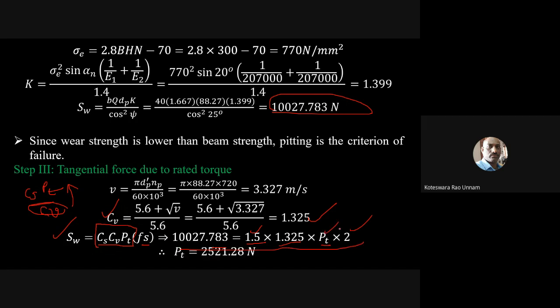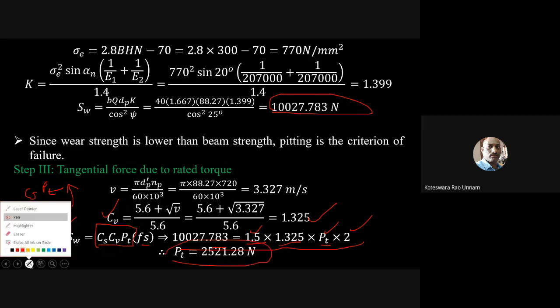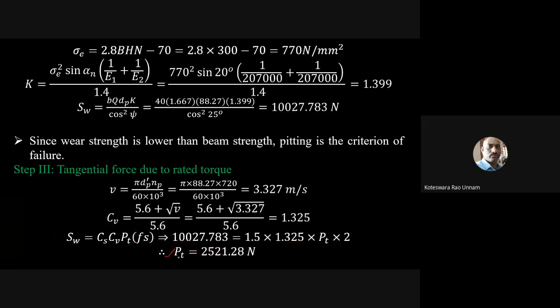Once you have PT, then you can calculate the torque transmitted. If you simplify this equation, you will get the tangential component of the force PT as 22,521.28 newtons.